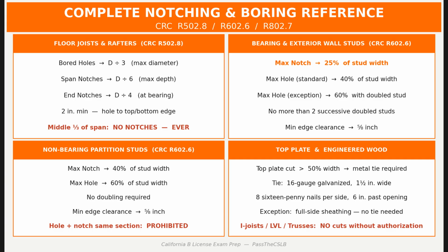Trap 1 is nominal versus actual dimensions. A 2x10 is 9 1/4 inches deep, not 10. A 2x8 is 7 1/4, not 8. A 2x12 is 11 1/4, not 12.